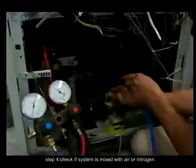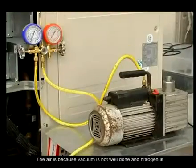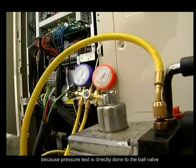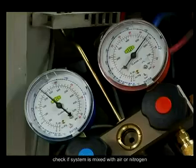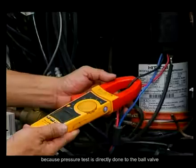Step 4. Check if the system is mixed with air or nitrogen. The air is because the vacuum is not well done, and nitrogen is because the pressure test is directly done to the ball valve.